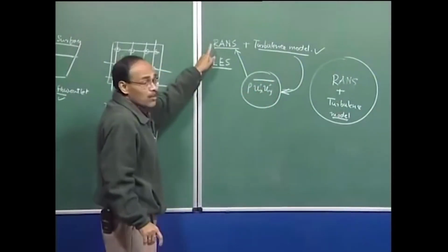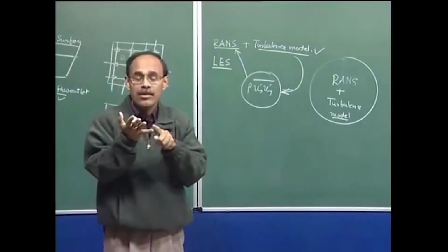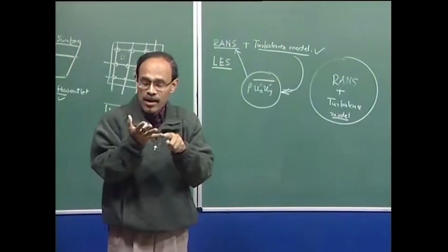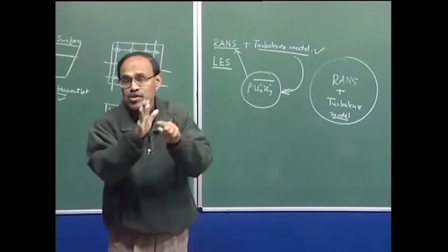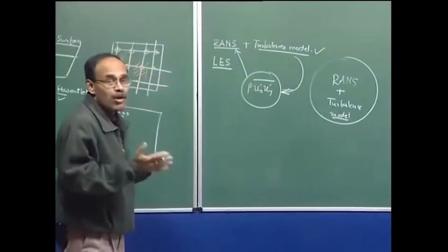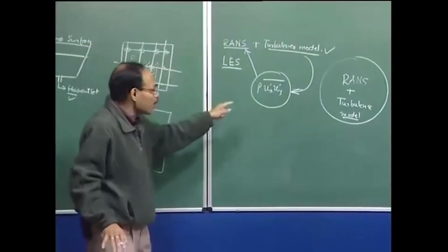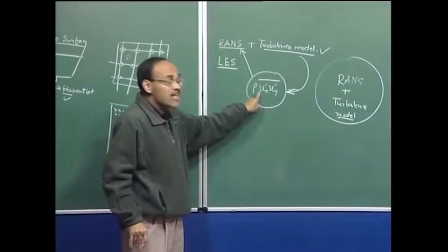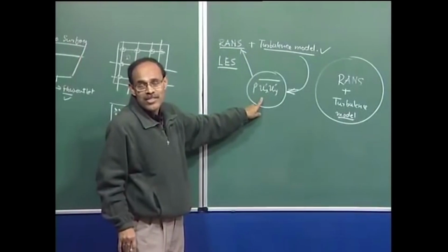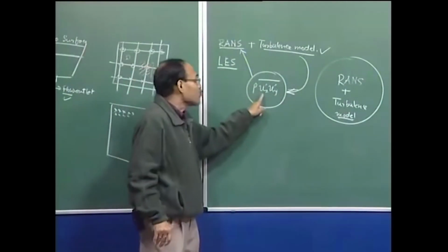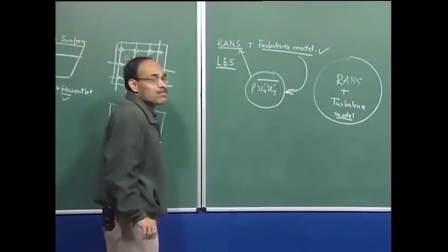So, I repeat again that we originally have 4 unknowns, u_x, u_y, u_z and p, and we have 4 equations, 3 conservation equations of motion and 1 continuity equation. So, the problem is well defined, but when you time average it, we still have those 4 unknowns, and on top of that we have additional unknowns which are the turbulent shear stresses. Unless these are prescribed, we cannot solve those equations in closed form. So how do you calculate this? This comes from the turbulence model. It is sufficient for you to know up to this particular point itself.